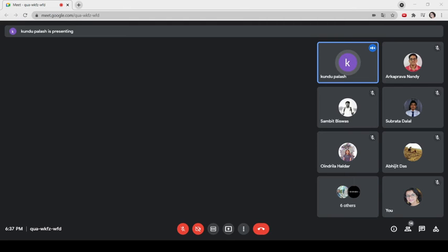You have to understand, after loading the values to the register, the timer must be started. How can the timer be started? By setting the TR bit in the TCON register. Initially, during the programming, the TR bit should be 0. Otherwise, the clock signal will be passed. But upon completion of the configuration of the timer, the last step is to set the TR bit. That is timer run. The TR is called the timer run control bit. Once the timer run control bit is set, the timer will start its operation.